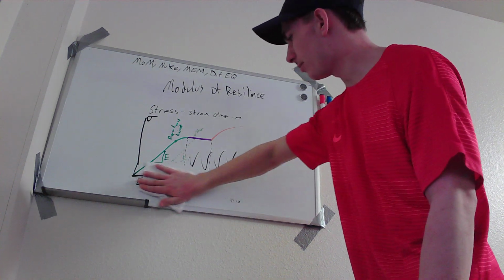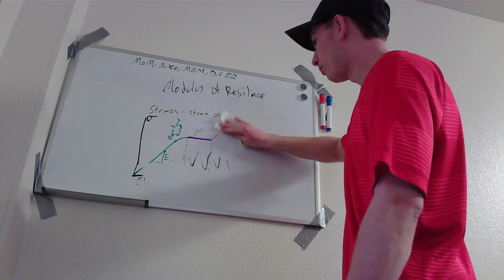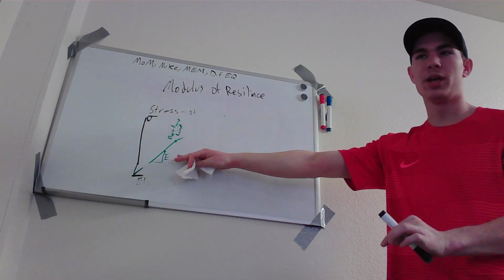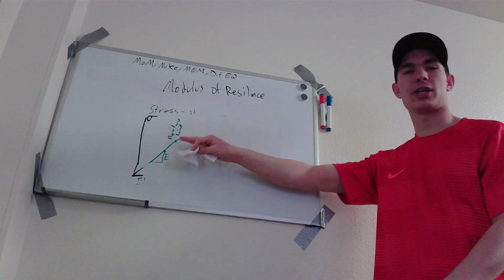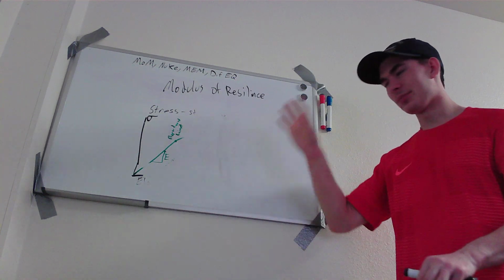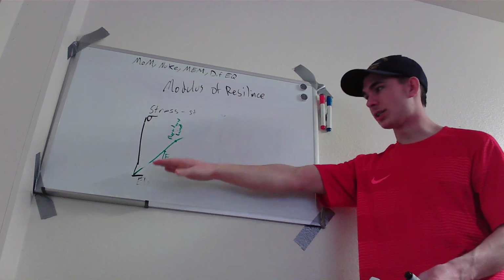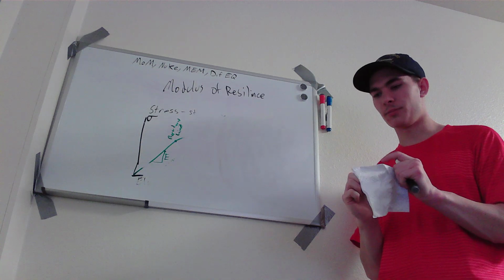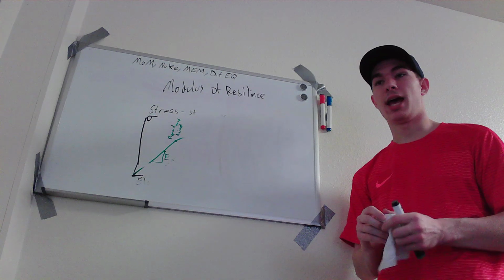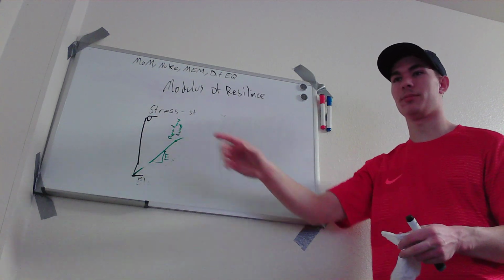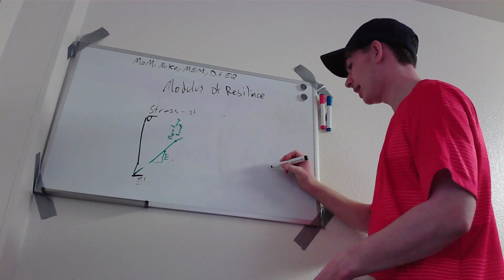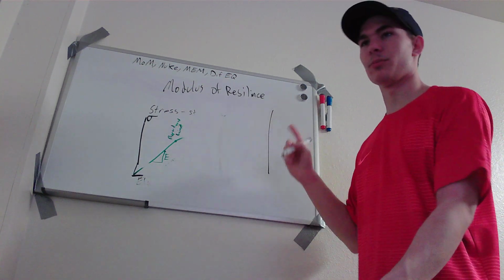We will be talking about some brittle materials and ductile materials. This stress strain diagram is only of ductile materials. A brittle material, kind of how I understand it so far, might strain a tiny bit, and then once you hit this proportional limit, a brittle material's slope of this E is going to be like a straight line.